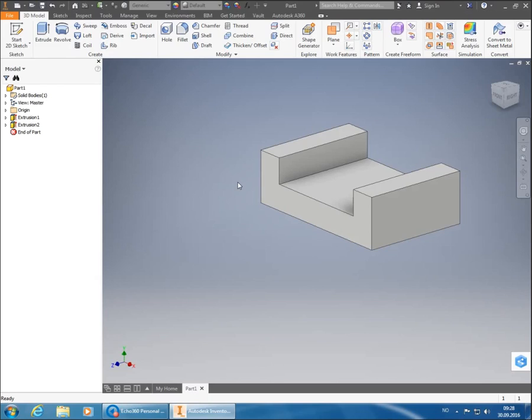Make sure that you're on the line. It says 60. Perfect. Just leave it. So leave the mouse. Press 50. When you click enter now, it's 60 plus 50. Finish sketch. And then press extrude. So now you choose your area.